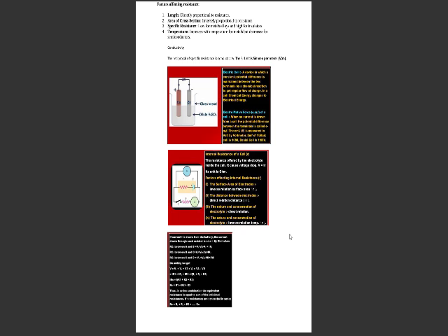Ohm meter is the specific resistivity of a specific length of a wire, and of the area of that specific length. That is called the specific resistivity of a material. Okay. Next, factors affecting resistance: length, area of cross section, specific resistance, as I told you already.